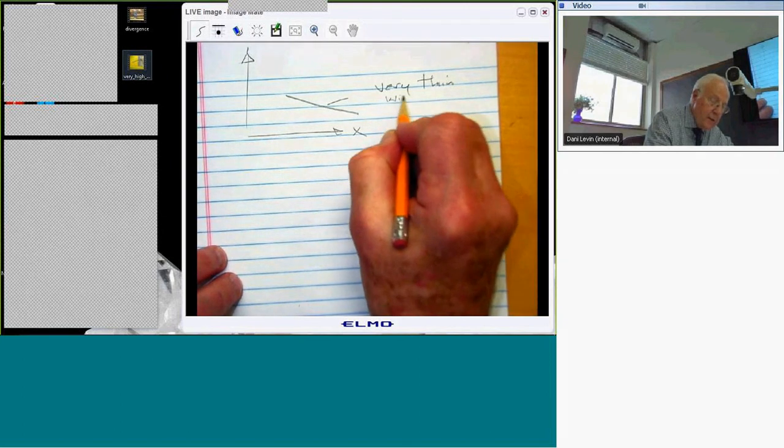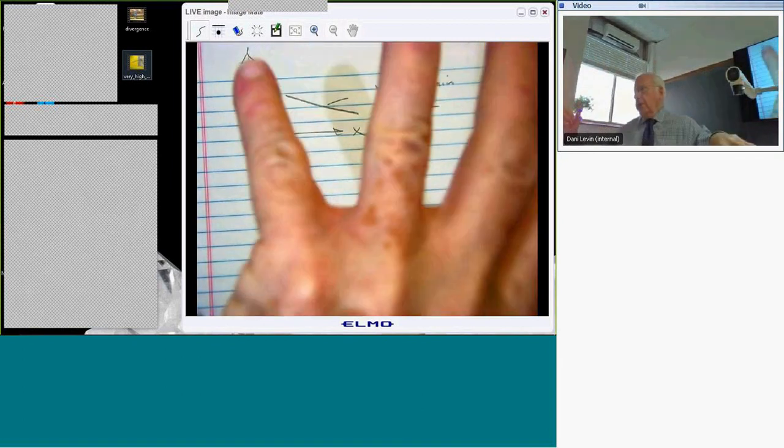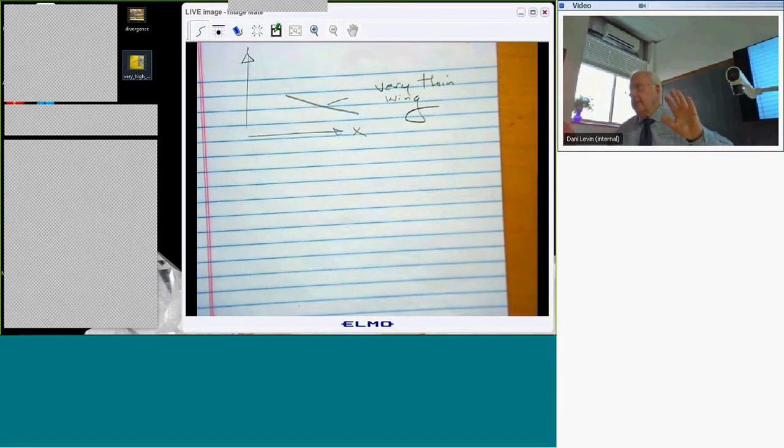By the way, it's a linear problem, right? So I can take any arbitrary distribution of W sub A, or deformation, and always write it as a symmetric part and an asymmetric part. And the part we've just done is the easy part, and usually a part you don't bother with in aeroelasticity because it doesn't lead to any net forces.